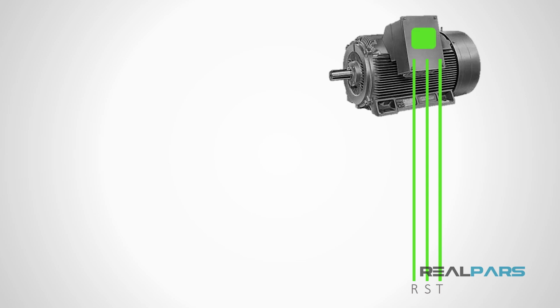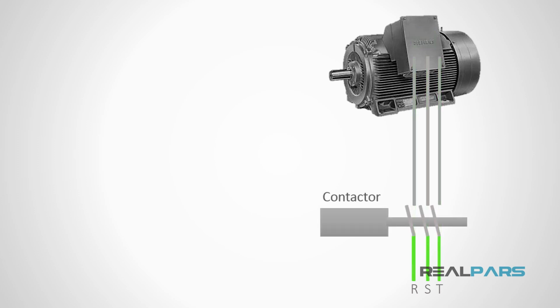on and off whenever required, which means that we need to introduce a switch so that we can turn the power on and off. The most commonly used switch in the industry for this purpose is a contactor. A contactor has two main parts, a coil and some open or closed contacts. It works by connecting these three phases to its open contacts and then applying a voltage to its coil.